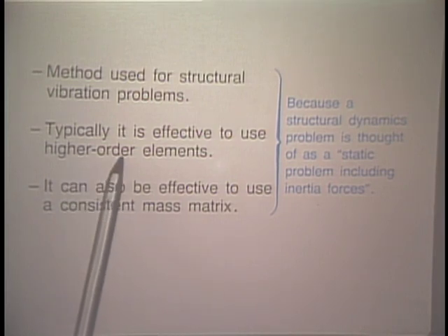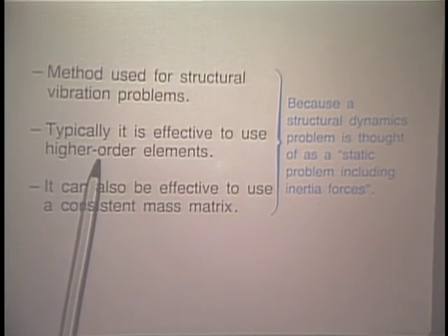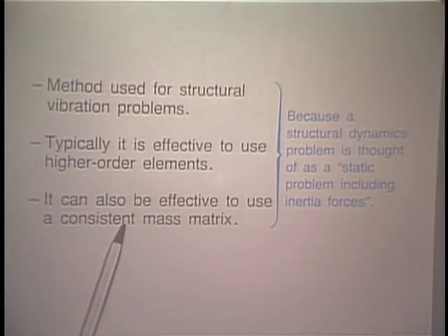I'm thinking here in particular of very high order elements such as cubic isoparametric shell elements, an element that we will talk about in a later lecture. With such an element you probably want to use a consistent mass matrix for the overall solution of the problem.